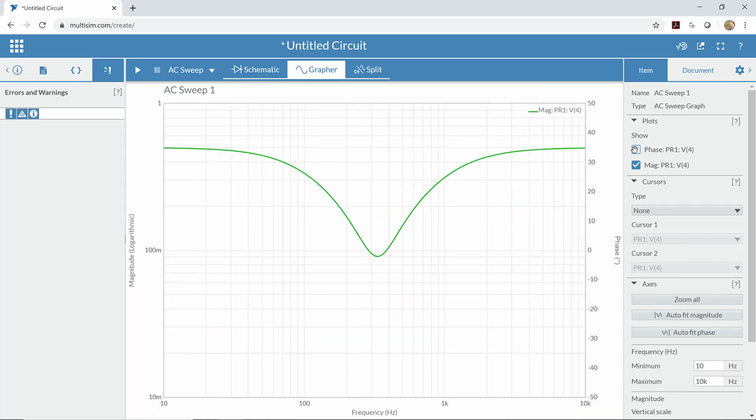All right, so this is the AC sweep. For low frequencies here, let's see what the voltage is there. If we hover over that, that's 497 milli, about 500 milli, which would be half of the amplitude. So when the low-pass filter is going up and down, the high-pass filter is holding still, and the middle point that we're measuring is moving about halfway.